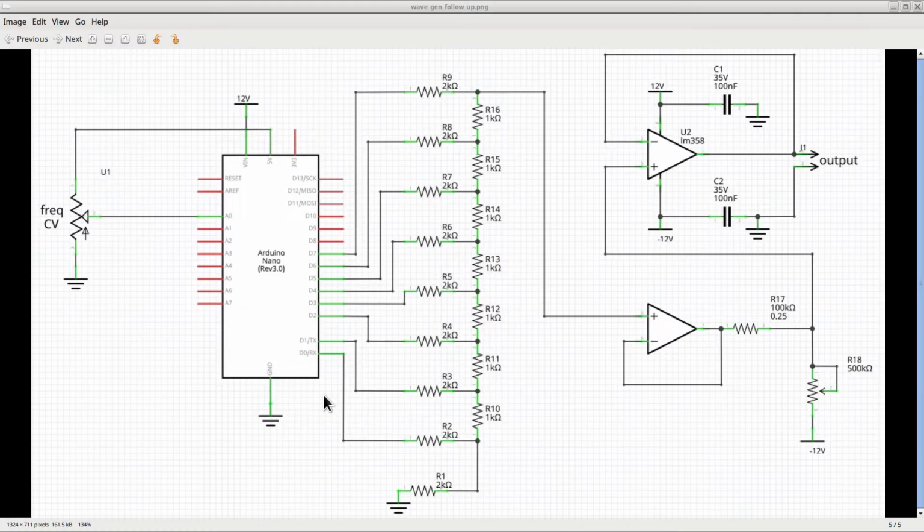Third, I used a voltage follower at the output of the digital to analog converter, so now we don't have to worry about drawing too much current from it. And fourth, I added a mixer to the circuit to add a negative DC component to the signal to cancel out the positive component already there. And this mixer takes the place of the capacitor used in the previous circuit. Why not, since I had an extra op-amp available in the LM358 IC that I used.